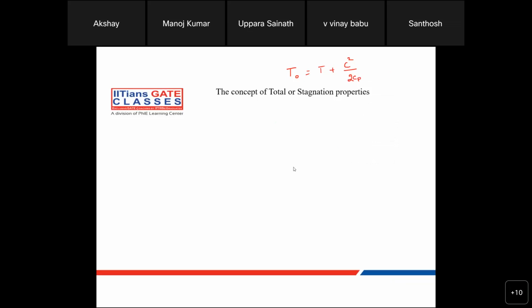Similarly, for total pressure, you might have defined it as when flow is brought to rest isentropically, right? The thing is that is actually a half-cooked definition. It is not just when a flow is brought to rest adiabatically, you cannot just define a total temperature like that. This is one more important aspect we miss while we read a textbook. Textbooks usually define a quantity when you bring it to zero velocity in a certain process, but that is the definition in a half-cooked way. So we will see what we are actually missing.